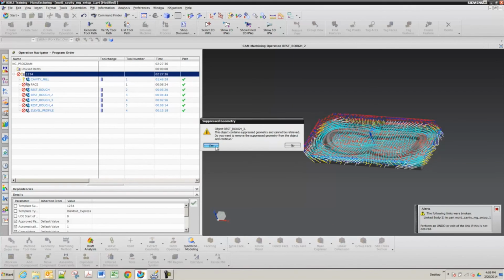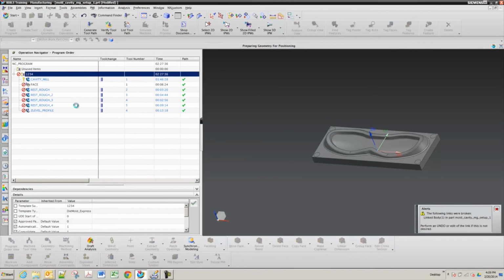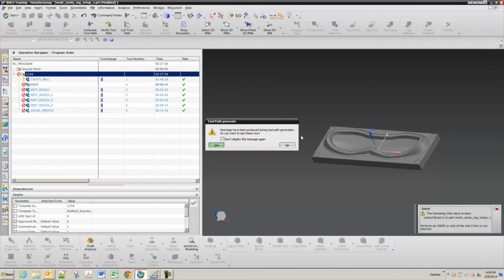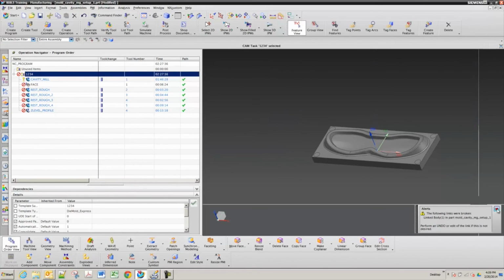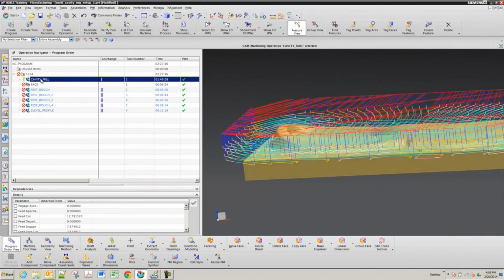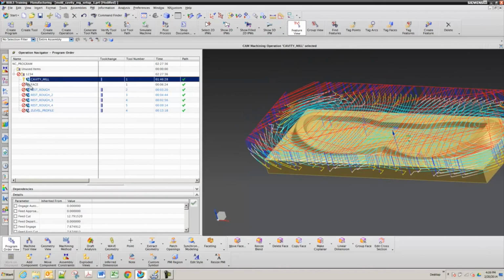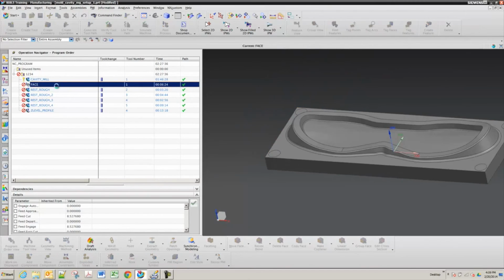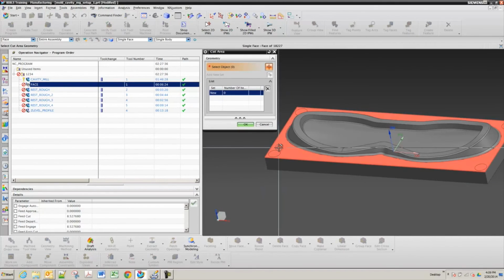Oh, I must have hit no. Yes. So we'll go fix those. So I gotta fix the first one. So hang on. Oh no, the face. What it was is the face doesn't have the floor, so I'd have to repick the floor on that. So hang on a second. Let me hit stop. Okay, so the cavity's fine, and like I said, cavity mill is very robust for replacement. But anything where you're having to pick geometry, I'd have to at least repick my floor.